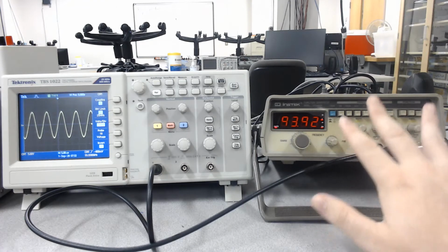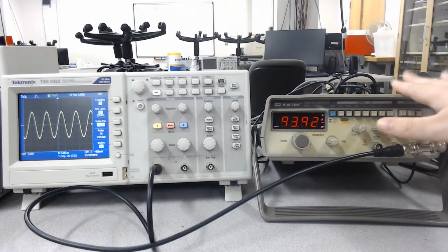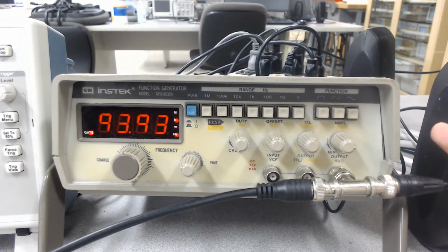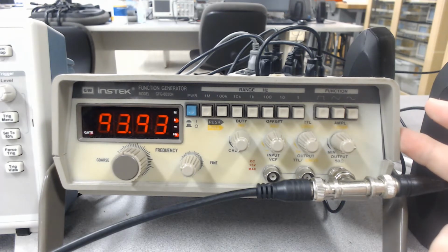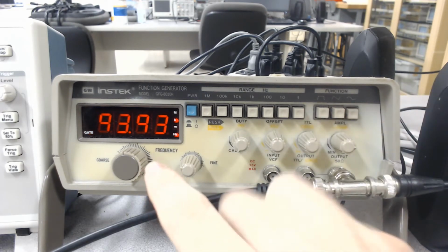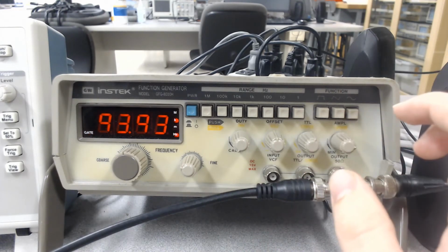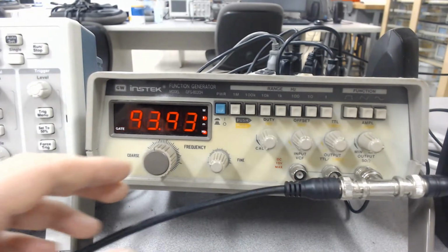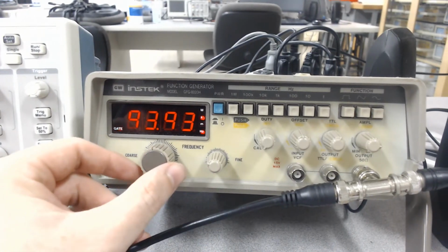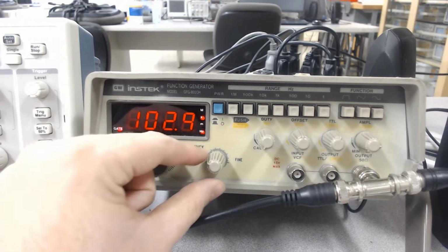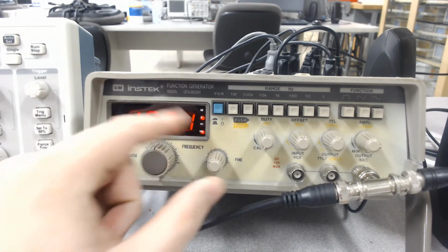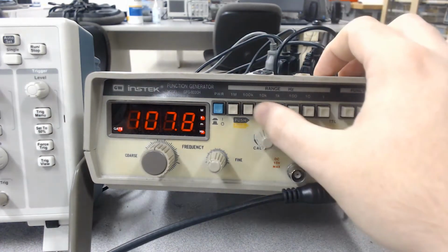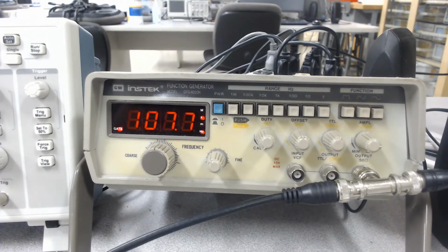First off, I'm going to zoom in on this function generator. All right, so this is a close-up of the function generator that I was just talking about. I'm going to go over what all these buttons do. You should already have completed this for the pre-lab, but just to reiterate, here are your knobs that adjust the frequency. The coarse knob and the fine knob adjust the frequency that's displayed here. Across here is the range setting. This will get you in the general area in which you want to read the frequencies.